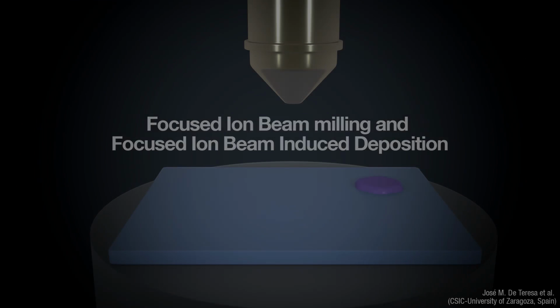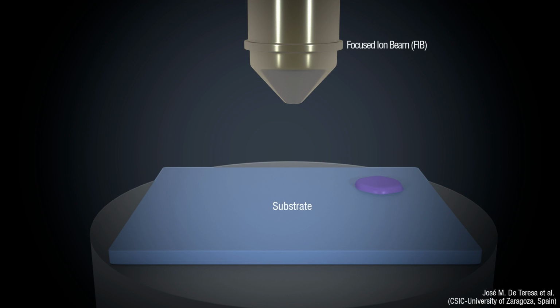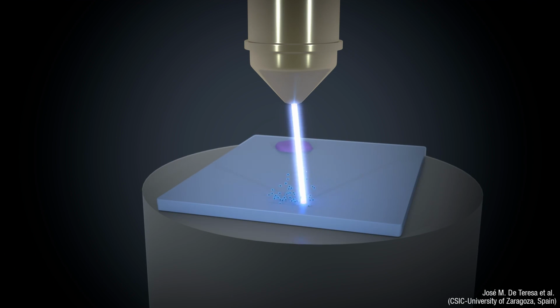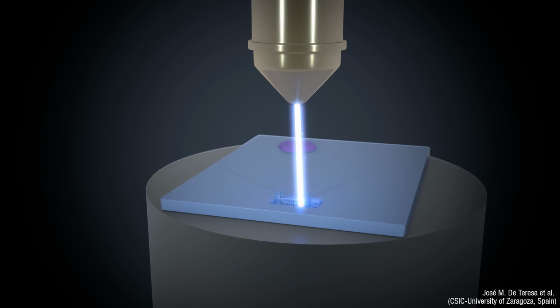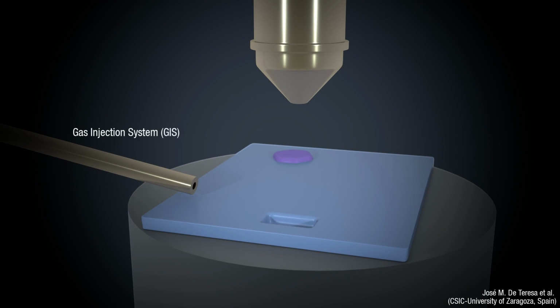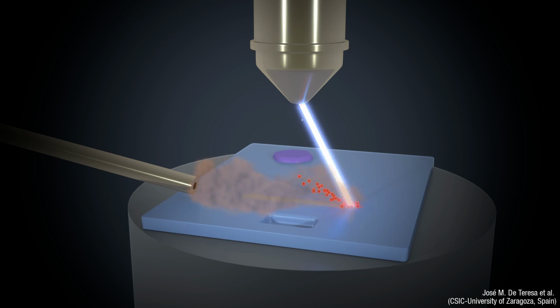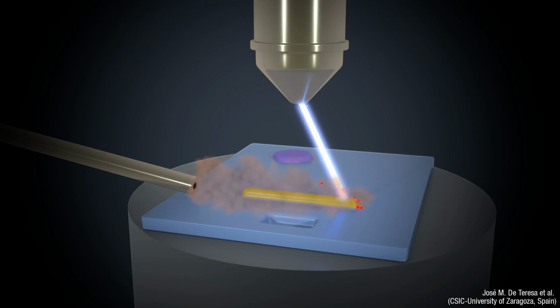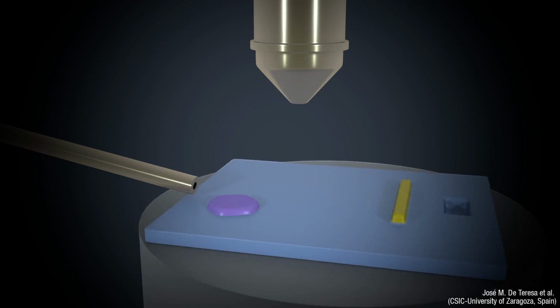You can see here the focused ion beam. This is similar to a scanning electron microscope. You have, in this case, a gallium ion source, or it can be a helium ion source. And then you can scan this ion beam on the surface and create a hole in the structure. This is called focused ion beam milling. But if you insert a gas injection system, you can inject a gas that is decomposed by the ion beam, and you can grow material.